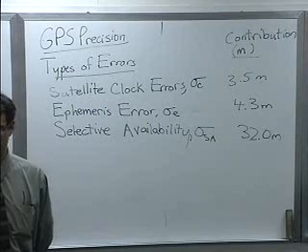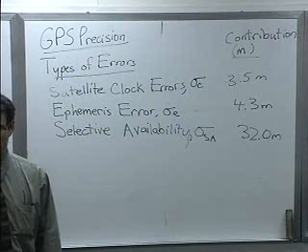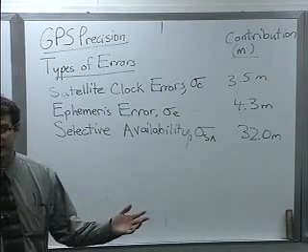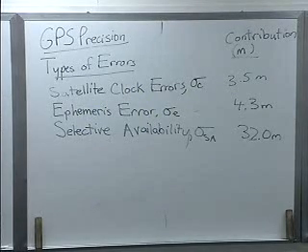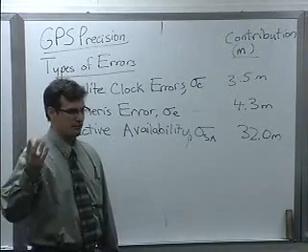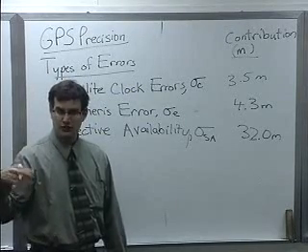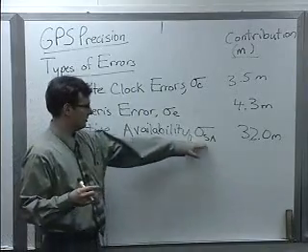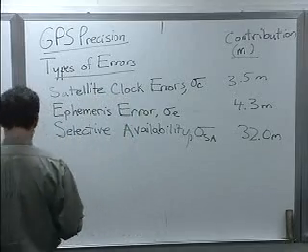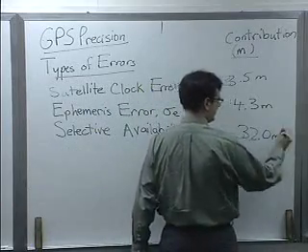And in 2000, they turned it off because they figured, well, this is being used by so many people, and it's become such an important part of everyday life that we'll go ahead and turn it back off. But who knows? One day they could turn it back on. So basically, they would swallow a chip in the PN sequence intentionally every so often, and that would introduce enough unpredictable error in the signal that you wouldn't be able to decode it without a special decoder. But normally, nowadays, this is actually 0.